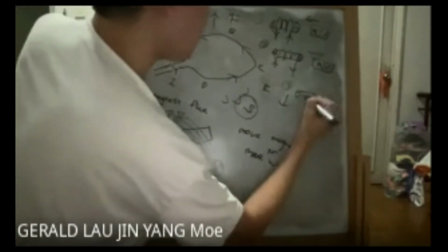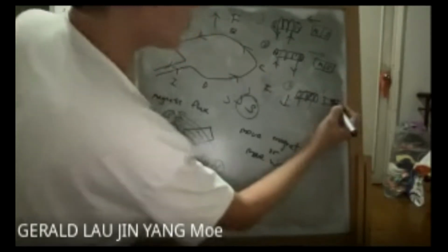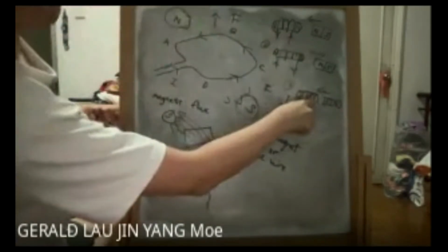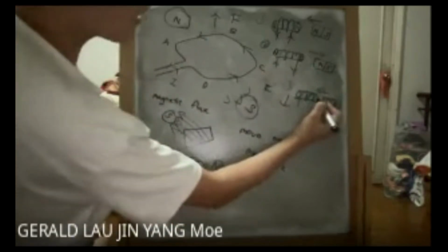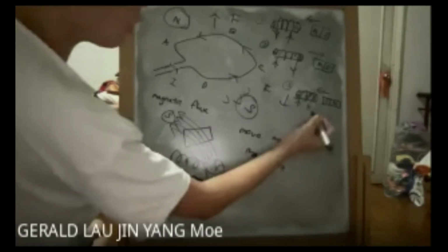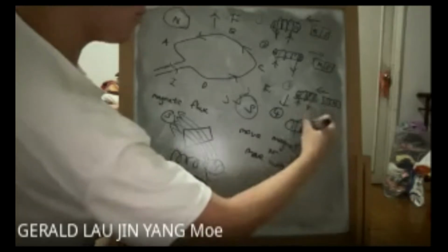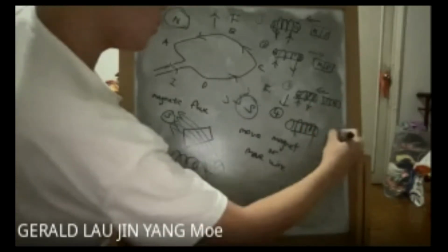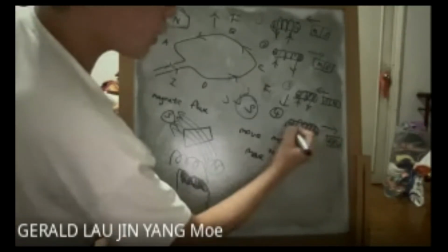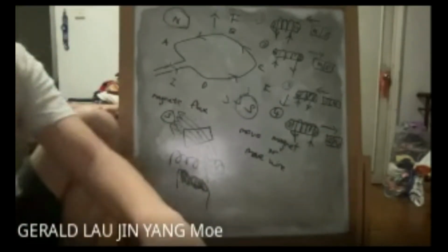Okay, and then the same thing happens for the rest. Solenoid again, and then let's say your magnet's south pole comes close. It wants to repel the magnet. So here automatically becomes south. Here north. So it flows from here to here. But if I move my south pole away from the solenoid, here becomes north. Here is south. So the current flows like this. So this is Lenz's law.